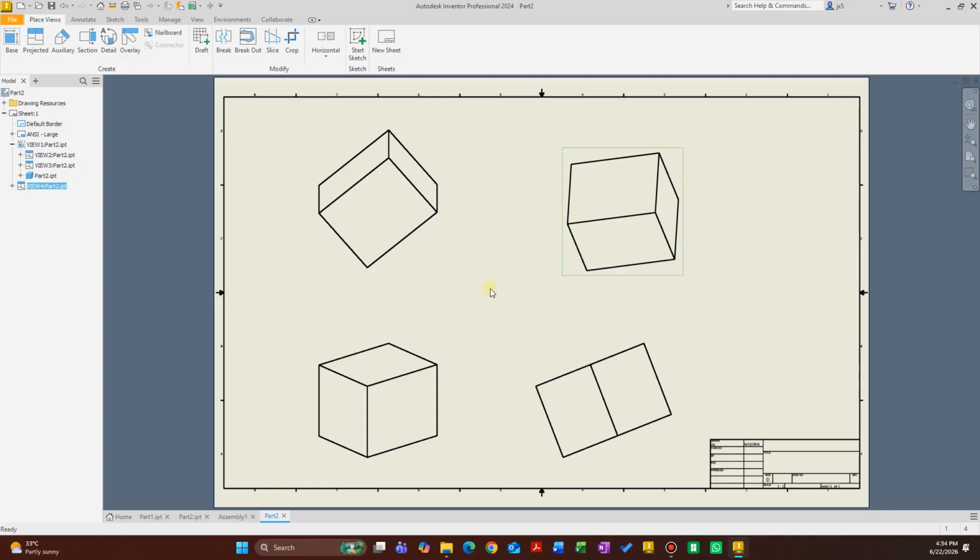And it doesn't even have to be a drawing for an individual component. It can be a drawing for the assembly. In that case, we can specify how those parts come together, and we can number those components, and we can give a bill of material. In the bill of material, we can even talk about how many of those parts are used in the assembly. We can give vendor information. We can talk about a lot of other details that we cannot cover in the part mode or the assembly mode.